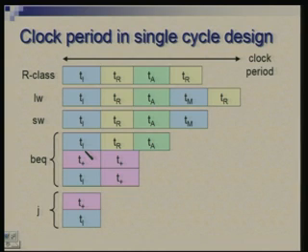From the first three cases I have dropped the T plus term, because that is invariably less than all these, and we do not really need to look at that. Now, you can very clearly see that with this kind of values, LW will dominate and dictate the clock period. So, the clock period would be from this point to this point. Remember that the horizontal axis is the time axis, I am showing along the timeline.